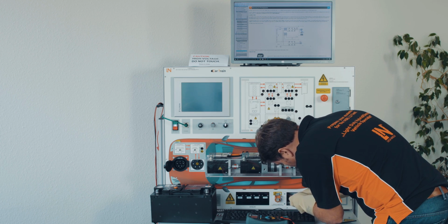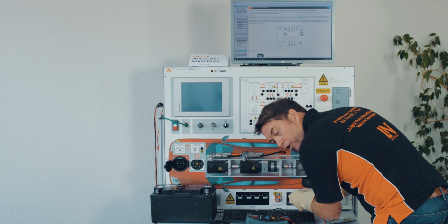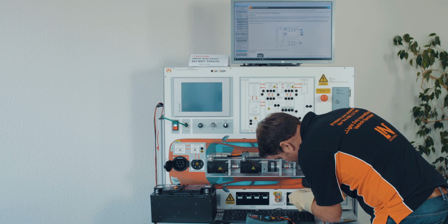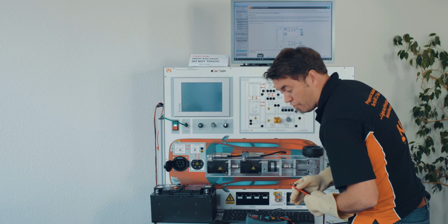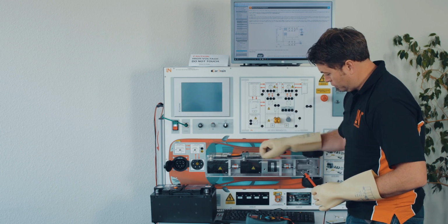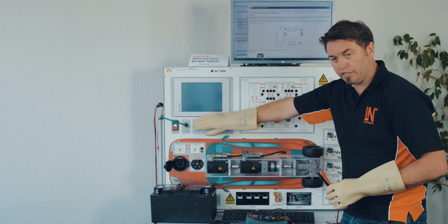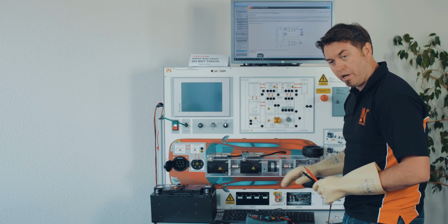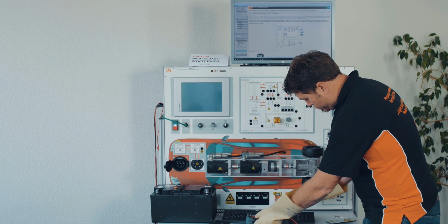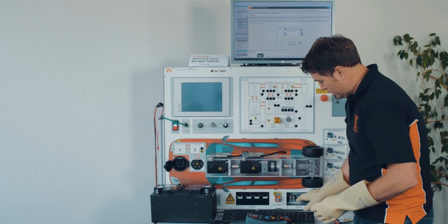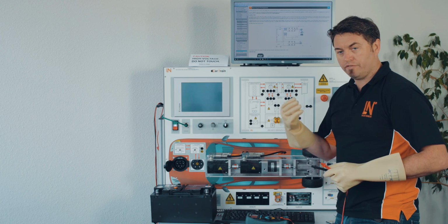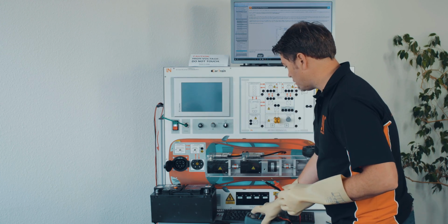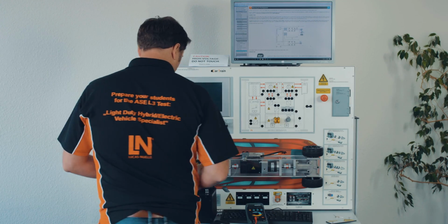and measure the connectors. So I've got two connectors here coming from the high voltage battery, and right there is now 0 volts. So the time it's taken me since I've shut down the ignition, had those capacitors discharged, there is 0 volts right here. Now I'm not quite ready yet. I need to go back to a live dead live. So I'm going to go back to my battery, 12-volt battery,